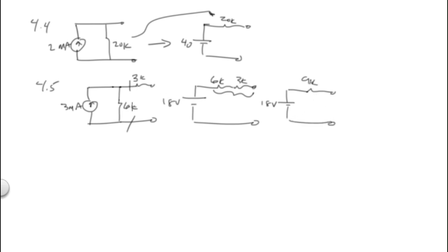So if you look at it, you cut this, and then you say convert this part to its Thevenin equivalent. 3 times 6 is 18. Move the resistor up, then you just combine the two, and you're done. So that's all you have to do for that one.